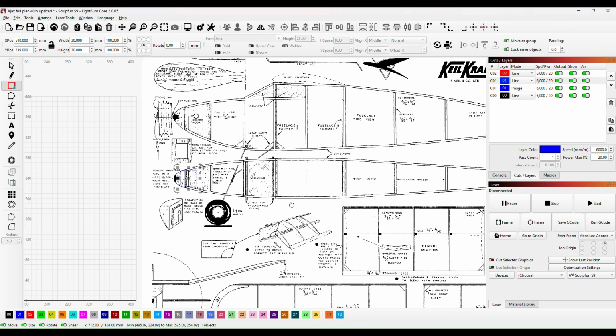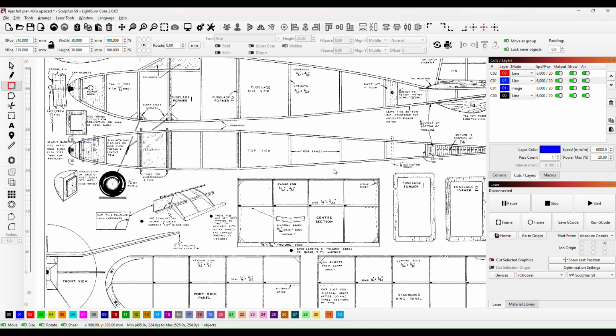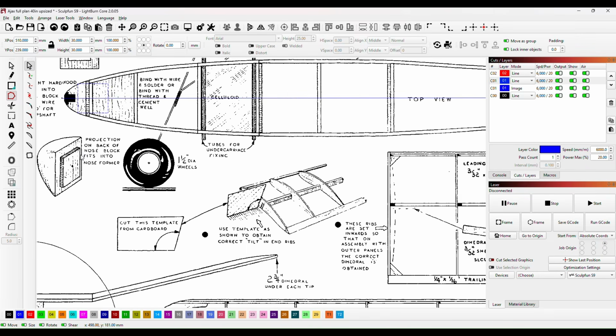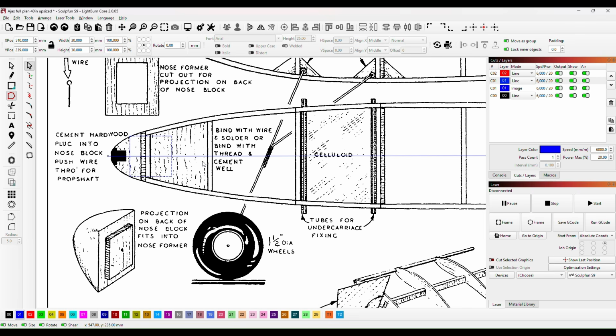In fact, just to help us, we'll put a centre line in on the whole thing. So if we just come from here and go back to there, we can make that our centre line. And if we zoom in a little and go to nodes, we can alter this node by pressing Control and Shift, and then we can take it up or down.